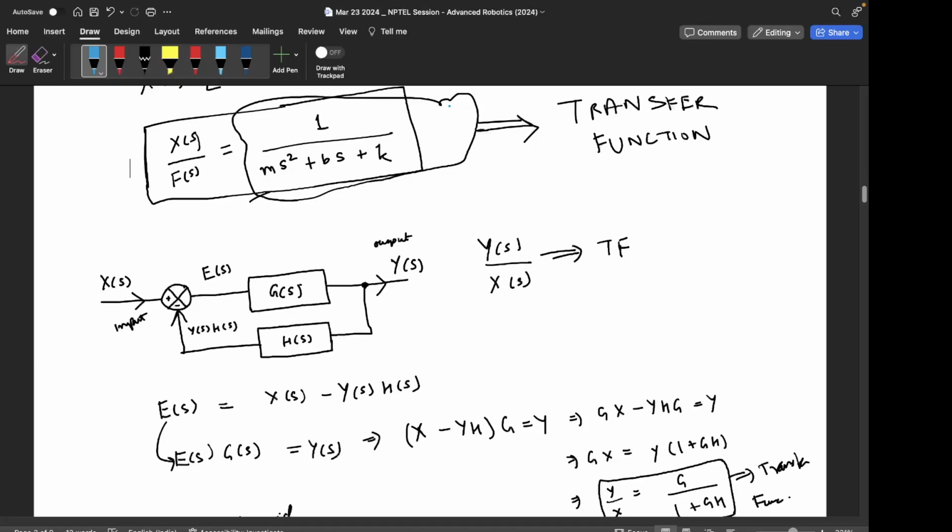So the very first time, yes, you're right, there will be no output, but it's not that without feedback from the output, some control input cannot be generated. It will be generated, right? It's like it will be xs minus 0, so es will be equal to xs, and it will go ahead like that. And once the system dynamics happens, there will be some output, and then the process will start. So yeah, it works like this.